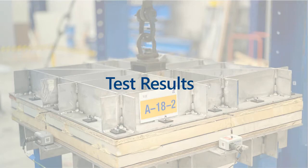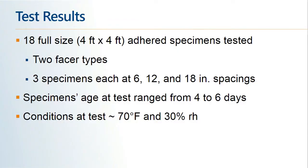Let's recap. We tested 18 full-sized 4-foot by 4-foot adhered specimens with 2 facer types, and there were 3 specimens each at 6, 12, and 18-inch ribbon spacings. The specimens were typically 4 to 6 days aged at the time of testing in our lab, and the conditions within our lab space were approximately 70 degrees Fahrenheit and 30% relative humidity.